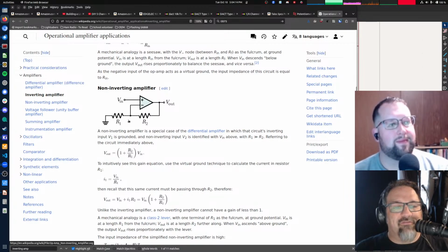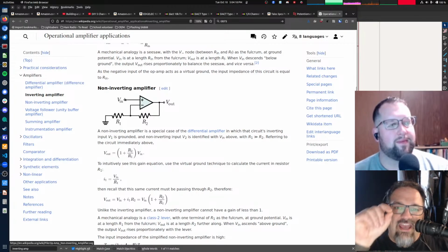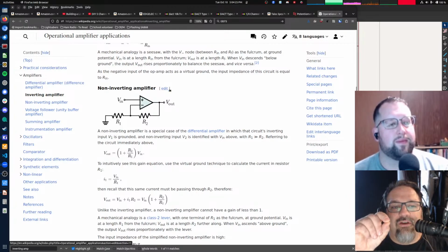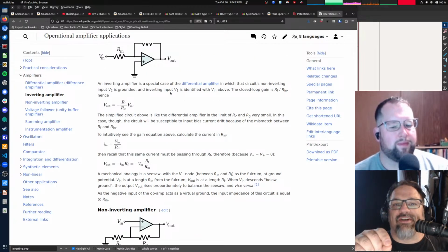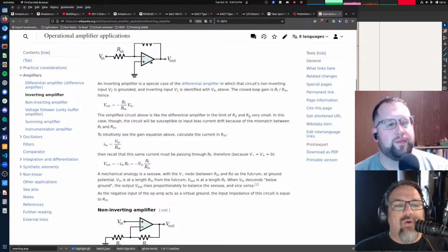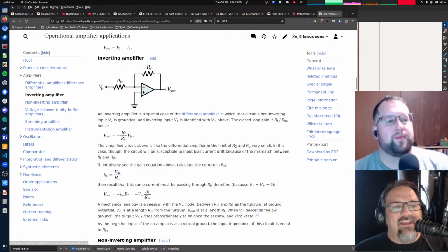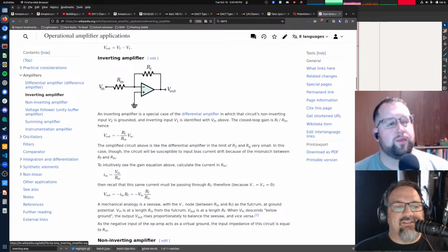The problem with the non-inverting amplifier is that it does not give your input a fixed ground voltage to dump its current into, right? So as a mixer, it wouldn't prevent the crosstalk that you're seeing. We explicitly want the inverting amplifier because this node is always the fixed voltage. That fixed voltage is explicitly what we're looking for here.